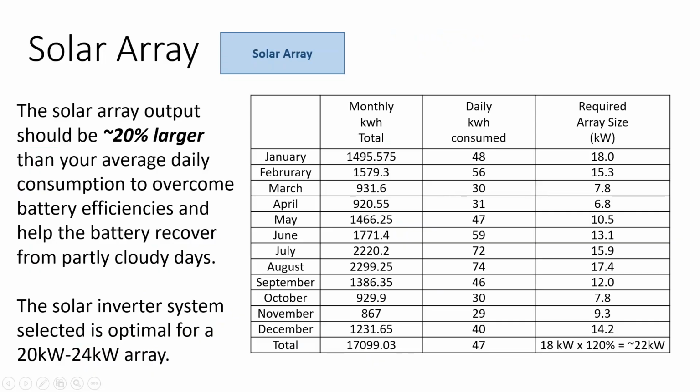Coming back to our question of oversizing then, normally I would do like a 12 kilowatt array to net meter this, and that might go on a 9 or 10 kilowatt inverter. Here I have an 18 kilowatt array. What size of inverter do I really need for that? If I divide by 20%, that might be a 15 kilowatt inverter, but I actually don't need that.